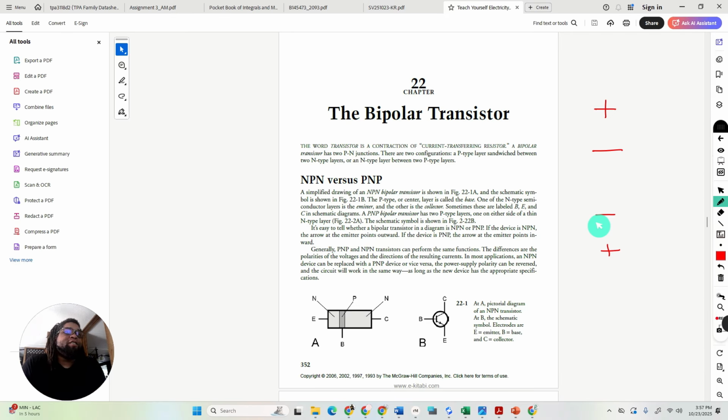What's more important here, and this is something he doesn't cover, is what NPN and PNP transistors are used for most commonly, because there is a place. PNP transistors are very useful. NPN are more common, but PNP are very useful. Why? PNP transistors you'll encounter mostly in current sourcing situations, which have to do with power supplies and with power amplification. Those are the two ways in which you'll see PNP transistors used the most. Everything else will just be NPN.